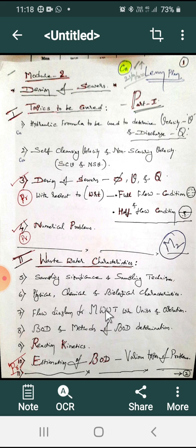Like this here also, from starting to end, in a water treatment plant you are getting the raw material from a reservoir or a dam. From the dam you cannot draw directly, so what we are going to do is provide some intake structures. The taking of water into the treatment plant through a system or a structure is called intake structure or intake works.